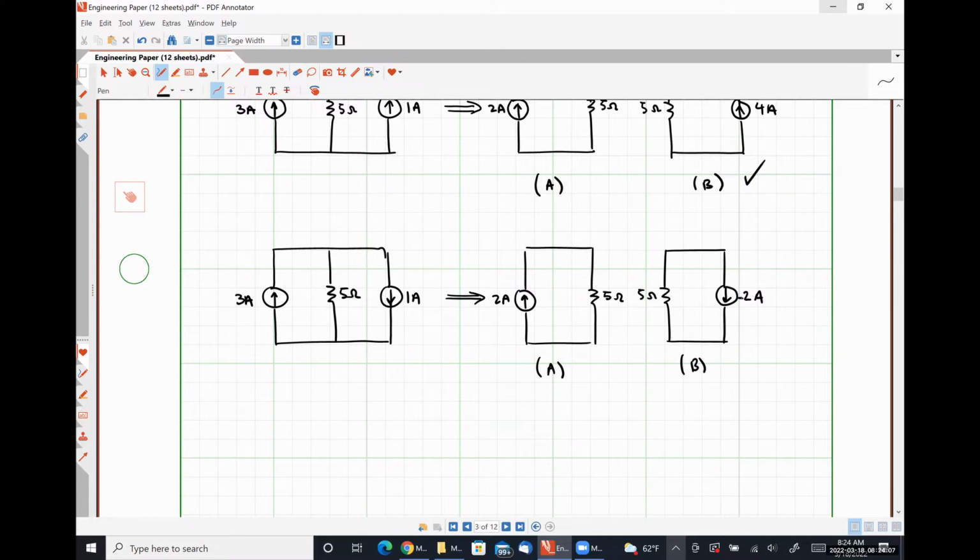These are literally identical representations. And we know this because if we want to change the direction of a current source, we simply multiply its magnitude by a factor of -1, which would literally give us the same circuit. So either one of those is perfectly acceptable. Would it matter particularly if I put the -2 amp source on the left as opposed to putting it on the right like I've drawn it here?